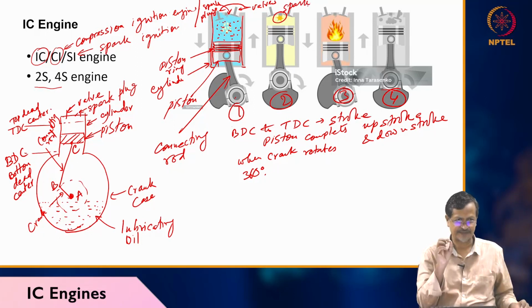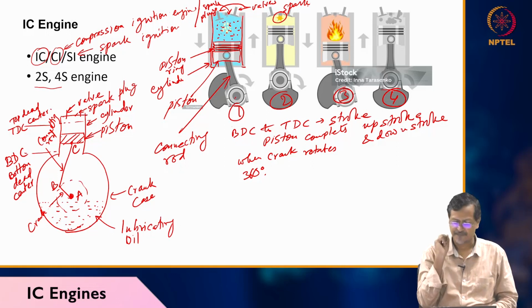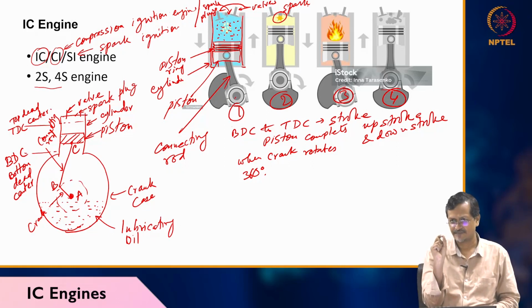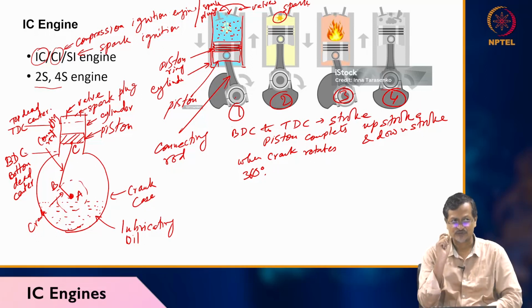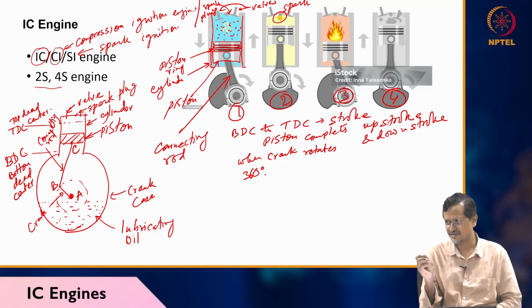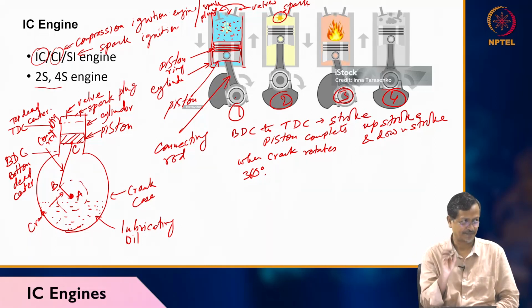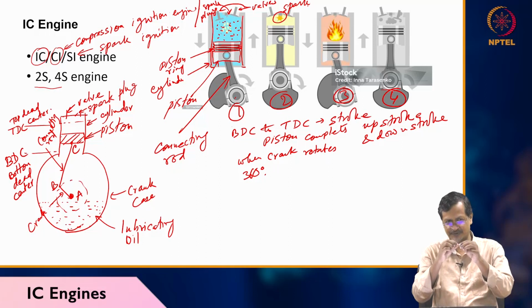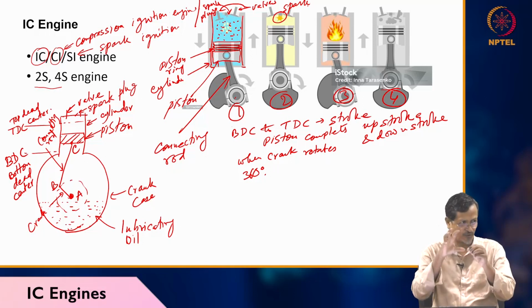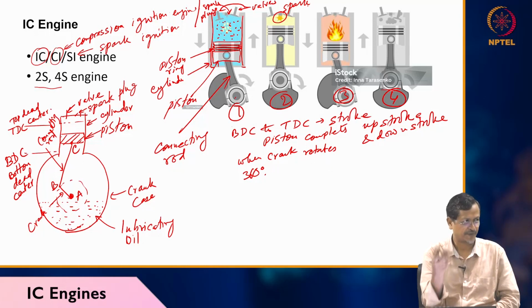A small spark means you give a small fire source. That will give a small reaction, an exothermic reaction. When fuel is burning, it is an exothermic reaction. Fuel plus air plus fire source creates an exothermic reaction, producing more heat. Heat will be transferred to other molecules, then the whole mass inside the cylinder, air and fuel mixture, will be burnt.